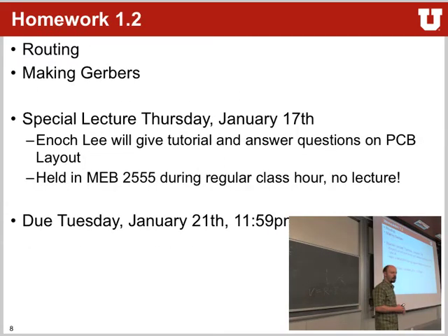All right, next homework. This is after the schematic, once you make the PCBs, we will do the routing and actually make Gerbers. The Gerbers are the files that you send off to the board house so they can produce your boards. That's the Gerber files. They also usually include a drill file, which will tell them exactly what size of drill they will use at which point in your board to make a hole into it. They will then plate that hole so there's actually a connection through the hole itself.